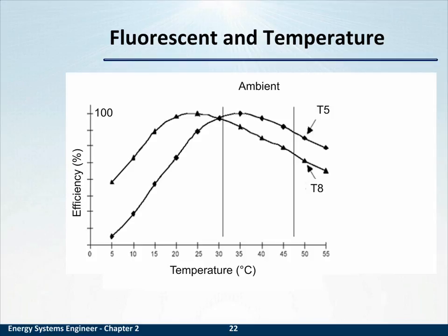But what about if you're relamping a cold storage facility? Is T5 always better? Well, this manufacturer's T5 and most manufacturers' T5s at cold temperature are not as efficient as a T8. So consider this just a graphic reminder to consider the context of your specific relamping project as it pertains to temperature.